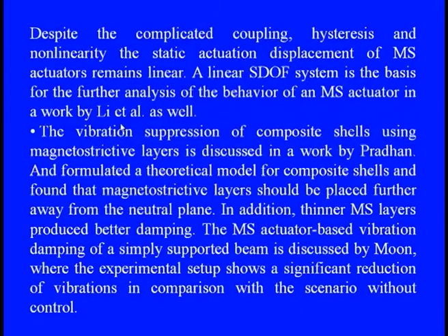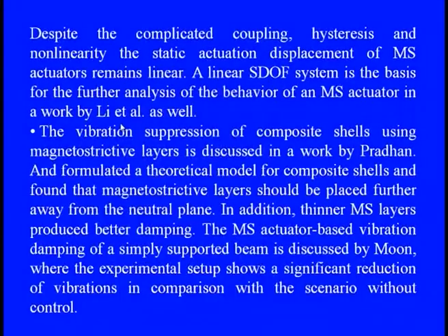are using the magnetostrictive layers in these shells, and through that you see there is a clear suppression of the vibrations. So they have framed the theoretical model for this composite shell, and they simply showed that along with this neutral plane, when these magnetostrictive layers are put in such a way that they are away from it, the MS layer can produce a good damping feature there itself.